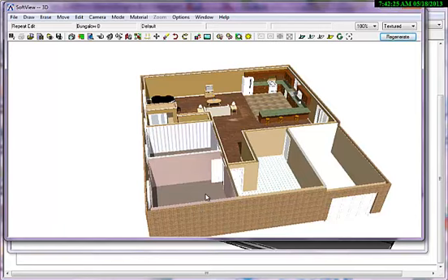When we put in the floor system, the computer put in the floor joist, the sill plate, and the subfloor, and that adds up to an extra 11.625 inches, so 11 5/8 of an inch. It doesn't do that up in the garage area because we've got a slab floor there. So what we've got to do is adjust the walls and make them the same height.